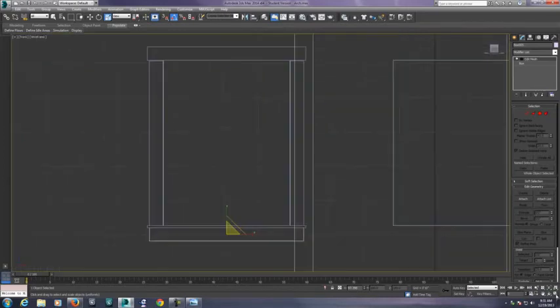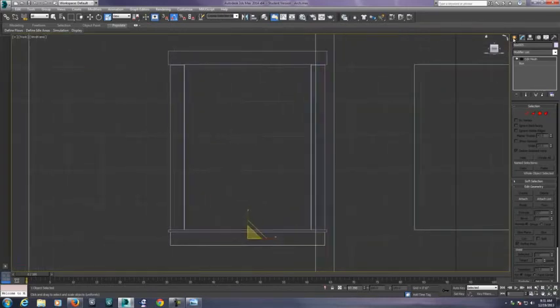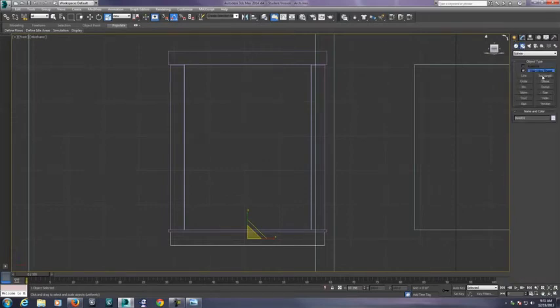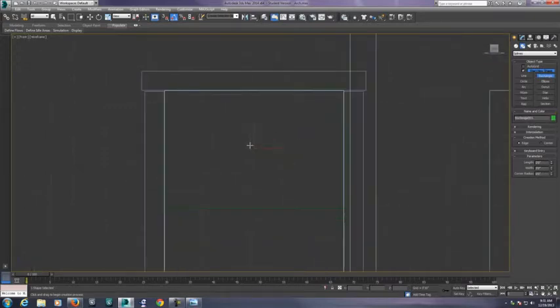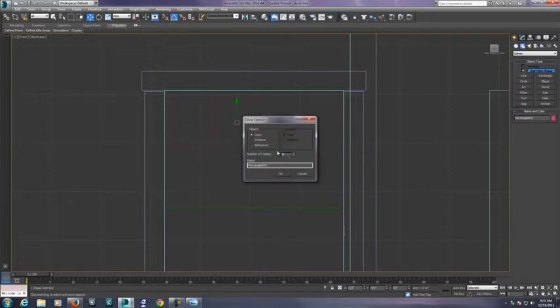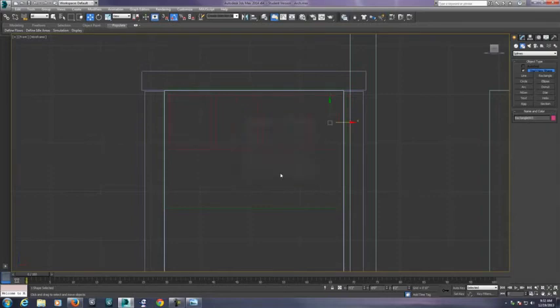And for the window, there are several different ways to do this as well. I am going to use a rectangle, and I'm going to overlap the casing just a little bit. I'm going to create half a window, and then make a series of these little boxes, and I'm going to use the array command here. So we'll do 3 copies, and then because it's a little bigger, I'm going to select all of them and scale them down so that they fit in there.